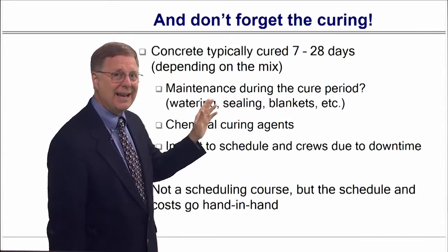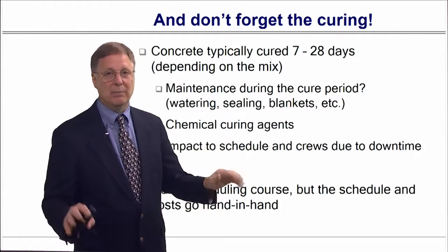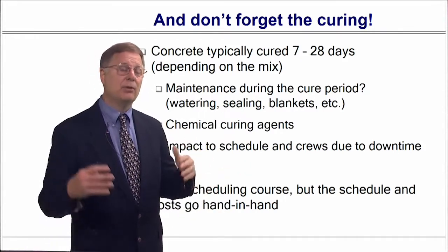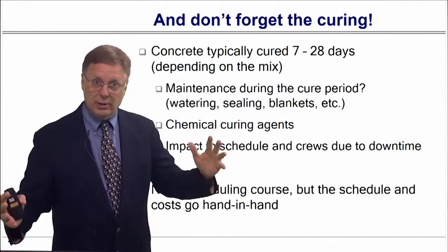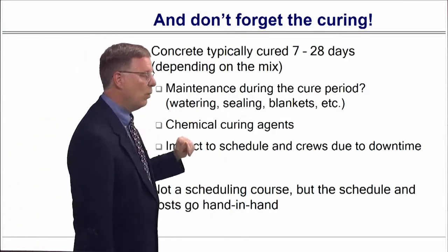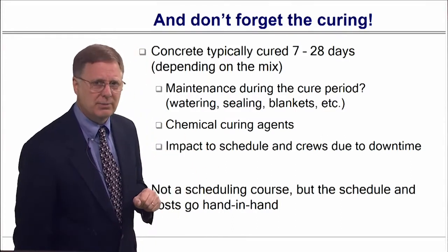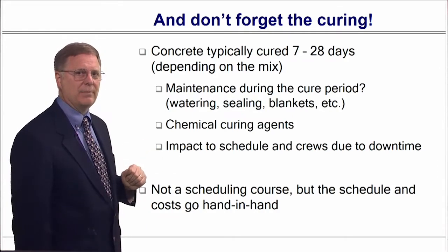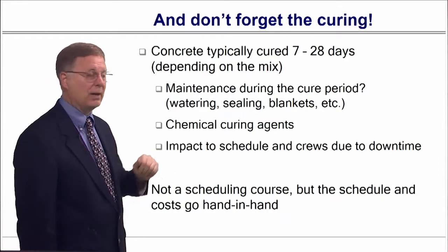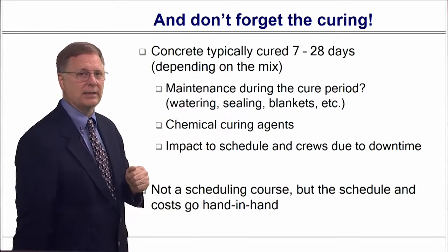And then how do you maintain it during the cure period? Because if you're in freezing temperatures, you've got to lay blankets on it. If you're in extremely hot temperatures, you've got to worry about it cooking too hot, depending upon the volume of concrete you have in one place. You've got watering of it, making sure it doesn't dry out, sealing it, and all kinds of different types of agents. Again, there's impacts to the crews and schedules because you have to wait for that amount of time before you do the next step or whatever you're going to place on top of there.